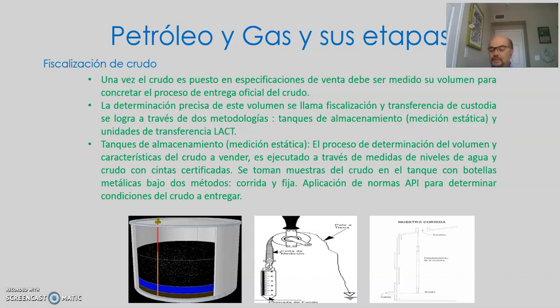Maybe just putting the oil and water in a tank, like we used to do in Venezuela, and just draining the water, because the water was separated with the use of chemicals, and not much chemical because it was a light oil. But when you have heavy oil, things change, and you have to do a lot of heating, a lot of things to put that oil at 0.5% water cut.